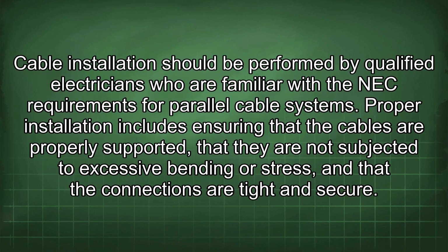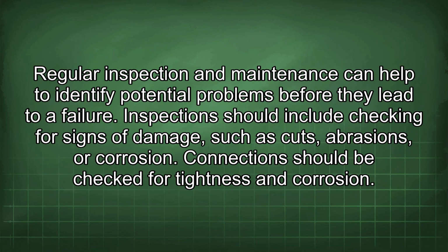Cable installation should be performed by qualified electricians who are familiar with the NEC requirements for parallel cable systems. Proper installation includes ensuring that the cables are properly supported, that they are not subjected to excessive bending or stress, and that the connections are tight and secure. Regular inspection and maintenance can help to identify potential problems before they lead to a failure.